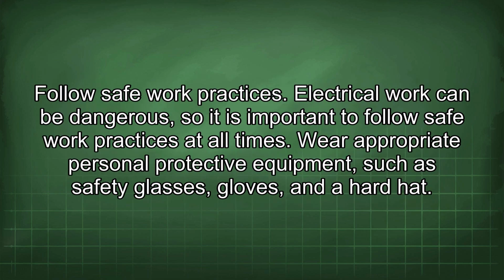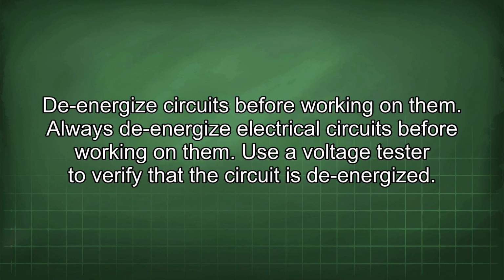Follow safe work practices. Electrical work can be dangerous, so it is important to follow safe work practices at all times. Wear appropriate personal protective equipment, such as safety glasses, gloves, and a hard hat. De-energize circuits before working on them. Always de-energize electrical circuits before working on them. Use a voltage tester to verify that the circuit is de-energized.